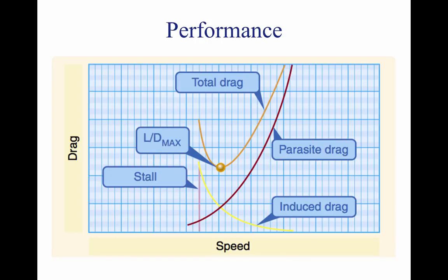Some of these factors are often directly opposed. For example, high speed versus short landing distance, long range versus great payload, and high rate of climb versus fuel economy. It is the preeminence of one or more of these factors that dictates differences between aircraft and explains the high degree of specialization found in modern aircraft. All of the principal components of flight performance involve steady-state flight conditions and equilibrium of the aircraft.